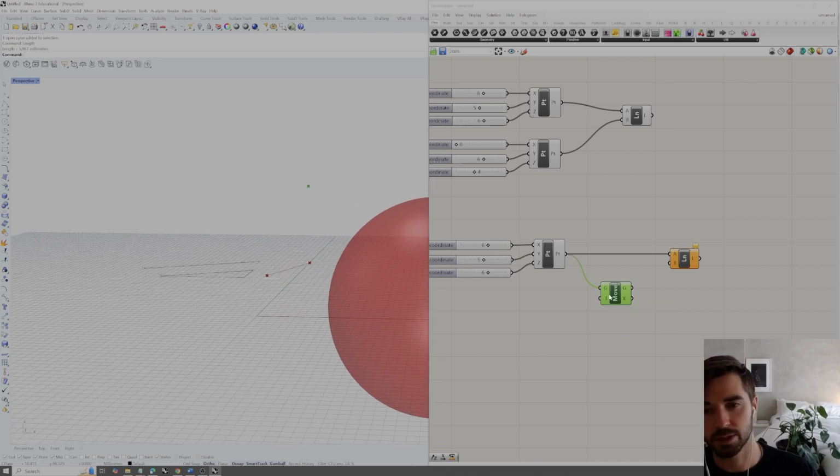If we wanted to change that vector, then we could double click, type vector. This is going to be a vector parameter, which we could draw out in space and reference into Grasshopper, or we could construct a vector using 2 points. As I mentioned in the first video, a vector is defined similarly to a line, which can be defined by 2 points in space, giving that directional vector, just like a line is defined by 2 points in space. Alternatively, we can define a vector like a point with just x, y, and z component values.